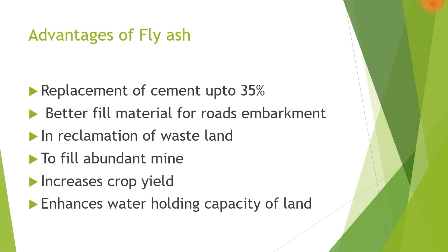Now talking about some advantages of fly ash. Cement can be replaced by fly ash up to 35%, thus reducing the cost of construction. Fly ash is a better fill material for road embankments. Fly ash can be used in reclamation of wasteland. Then fly ash can be used to fill abandoned mines, and most importantly fly ash can increase the crop yield in small units and it also enhances the water holding capacity of the land.